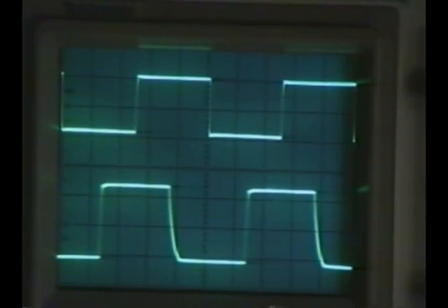Actually, this one doesn't operate from 0 to 180. I haven't used one of these for a long time, but I believe the phase detector really only works from about 20 degrees to 160, but I can't remember. It's something like that, but you get the idea. So in other words, what it does is it locks around 90 degrees. So right now, it's locked. It's very near the free run frequency.